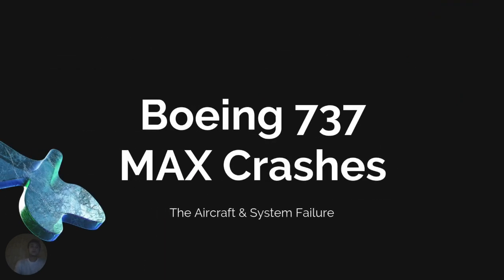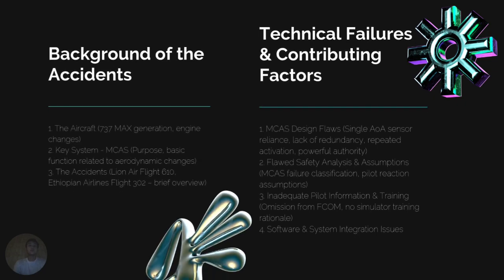The Boeing 737 MAX is a new version of the 737 airplane. It had bigger engines to save fuel, but these engines made the plane's nose go up too much in the air, which could cause a stall. So Boeing added a system called MCAS to push the nose down. The problem is that MCAS uses data from only one sensor. If that sensor gave wrong data, MCAS would push the nose down even if it was not needed.